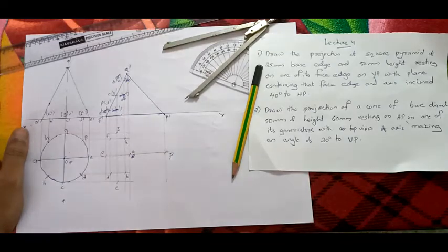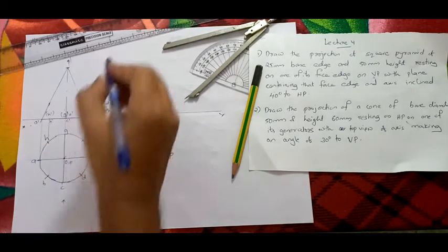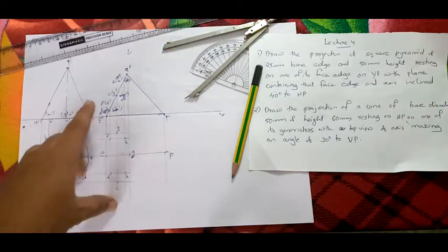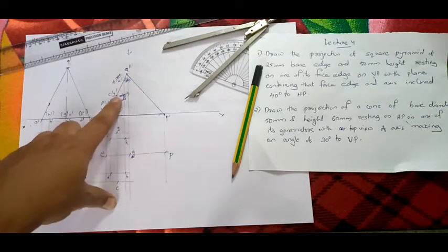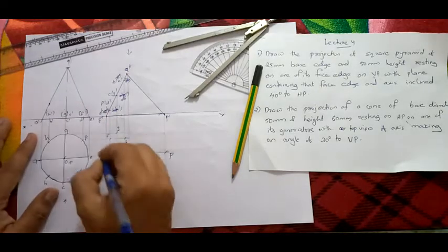So it's a change. Now what I am going to tell you is how to draw the visible lines. There are only two possibilities for a cone, that is either the base is visible or the base is not visible. So I will show both the cases. First, in this case here the base is visible, right? O is nearer to you than P, so here the base is visible. Base is visible means draw the base.